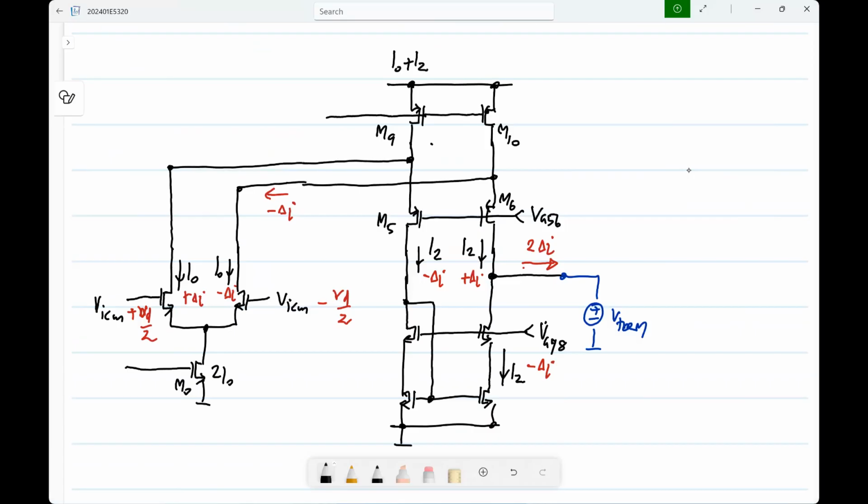I0 is whatever bias current you want to have in the first stage transistors, and I2 is whatever bias current you want to have in the second stage transistors. And of course, this is M3, M4, and M7, M8. They are numbered such that functionally they are the same between this and the telescopic cascode op amp. Is this fine?